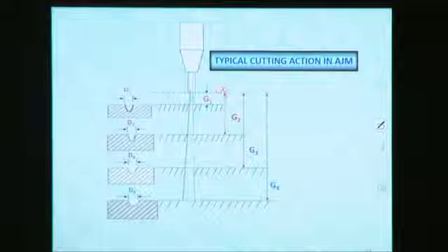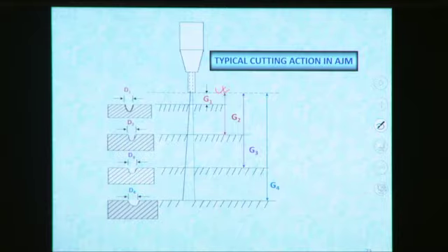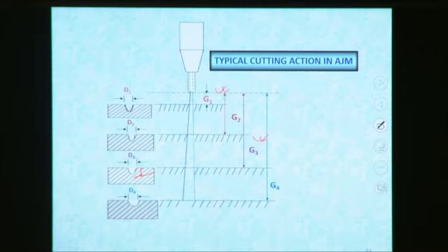If we consider G3 as the stand-off distance, the crater diameter increases, but the depth of indentation slightly reduces. It is lesser than in the case of G1. When we use G4, the crater diameter is D4, and the depth of indentation reduces further.